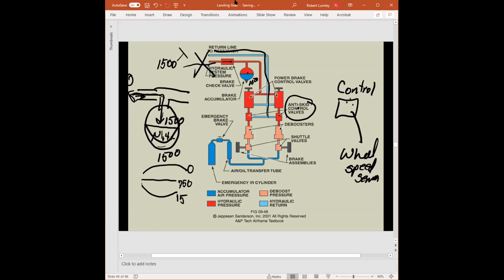Unlike ABS, which mainly just releases all the pressure to the brake to get the wheel spinning again, our system many times doesn't release all the pressure, but just enough to allow that wheel to regain its speed, and specifically back to the speed that it should have been at. The control box is very elaborate, okay? But really, there's only 3 components to it.